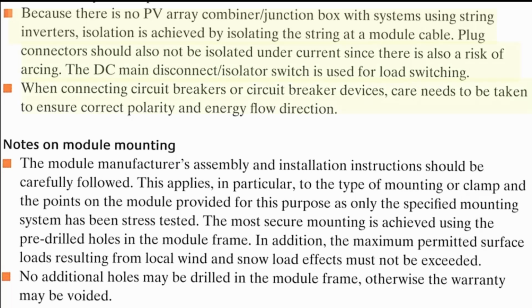Notes for module mounting. Sure, you should consider the manufacturer's assembly installation instructions. Also, if you use very thin framing or even frameless modules, you should really consider the recommendations of the manufacturer, because there has to be a certain size and certain position of the mounting clamps at the modules. Otherwise, there's a danger that the modules will break under high snow load or high wind speed conditions.